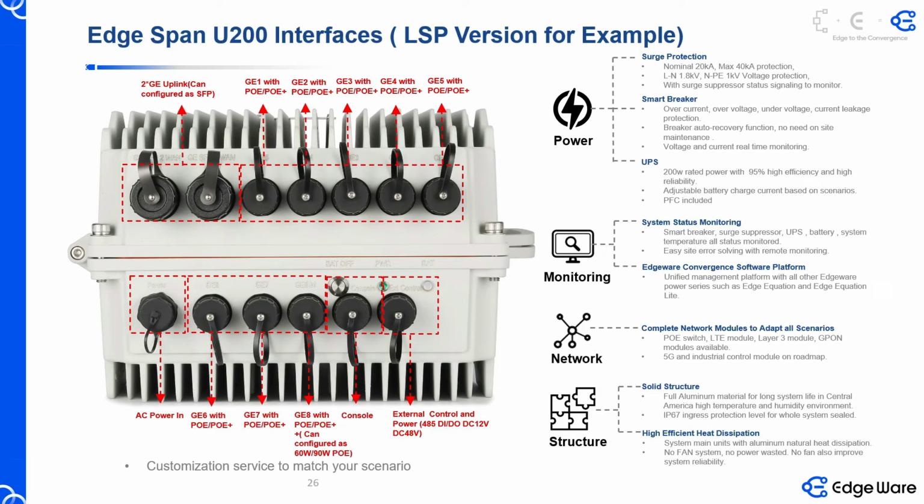So I don't really agree with deploying an indoor 19-inch rack, this kind of typical 1 kVA, 2 kVA UPS, inside outdoors. That's not a good way to solve the problem, and that UPS is designed for indoor usage.